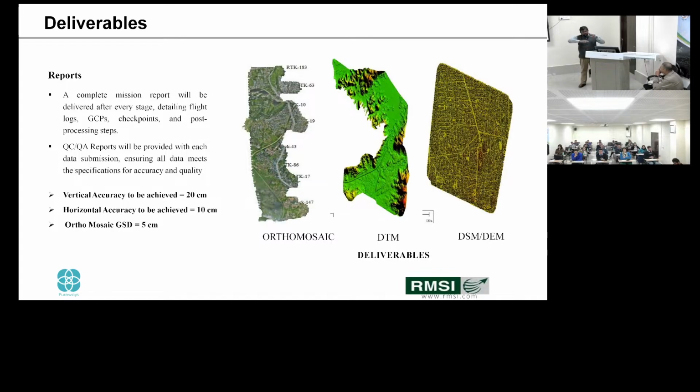A very unified surface. You will not see any minute detail, just a blanket wrapped over this entire surface, but it will give you the height, the lowest point, and how many trees. It's a complete blanket on the terrain. Nothing has been removed. That's called the digital surface model. It has its own utility. I'll come back to it later.